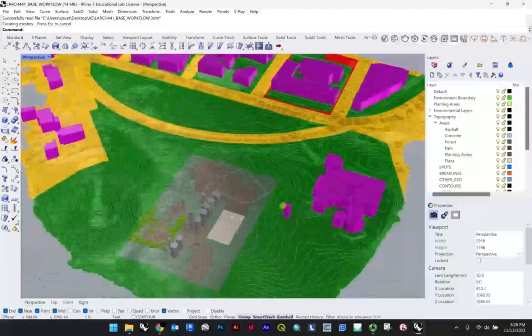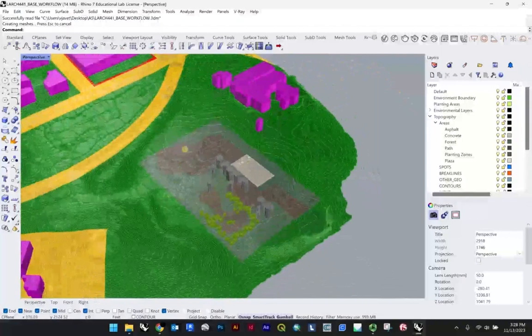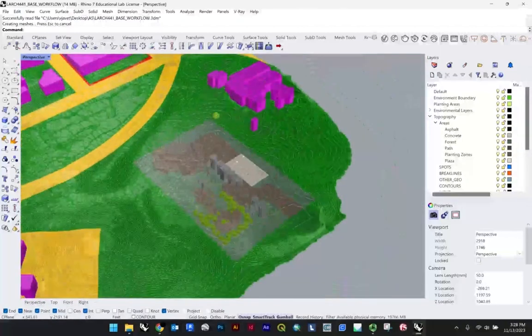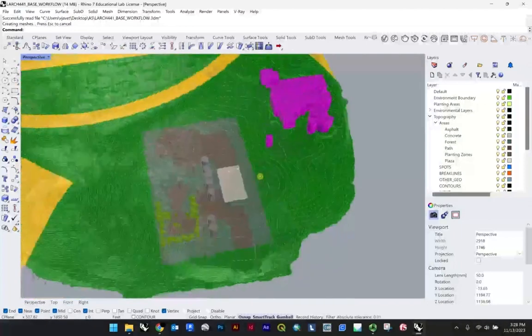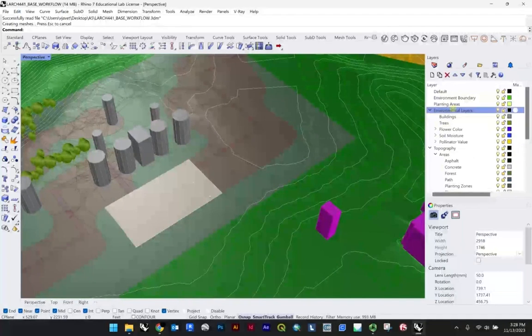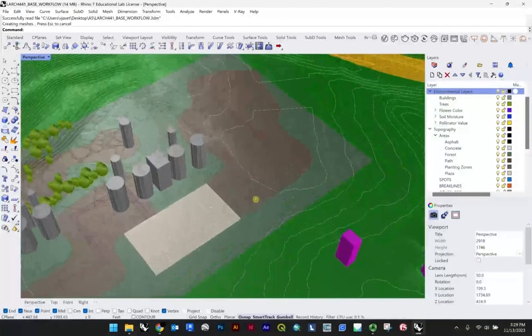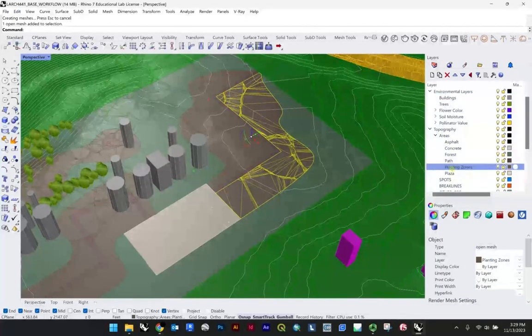And so just really quickly to update you on the file, this has changed again a little bit based on probably where we left off, which was, in the Revit module, we had designated essentially a site boundary within the Gasworks site itself. Now what you'll see here is I actually have a bunch of different subcategories where I've changed my naming convention for my layers. And I'll circle back to this a little later, but these naming conventions, from topography and then areas within topography. And then within the areas layer, there's actually another sublayer. In this case, Planting Zones, capital P and capital Z with a space.